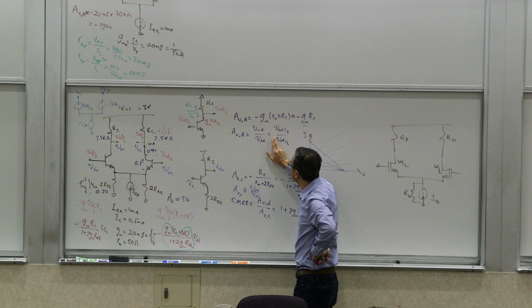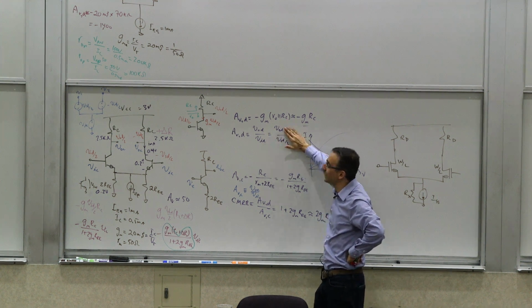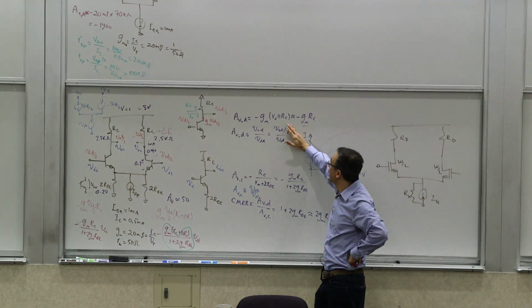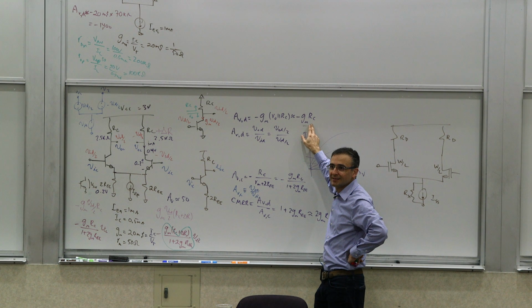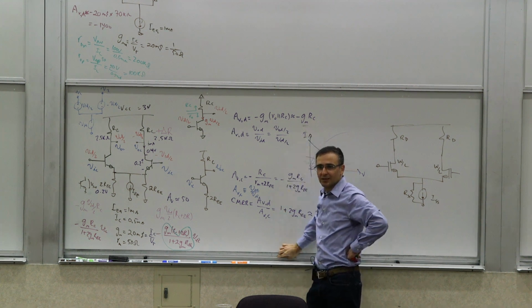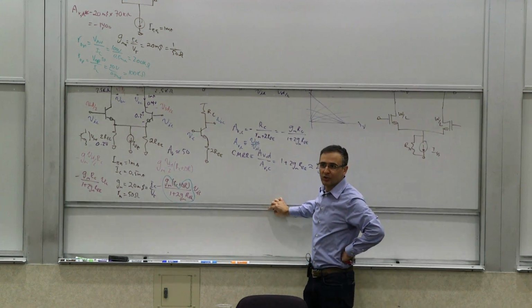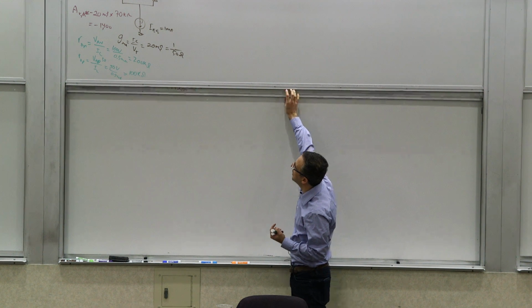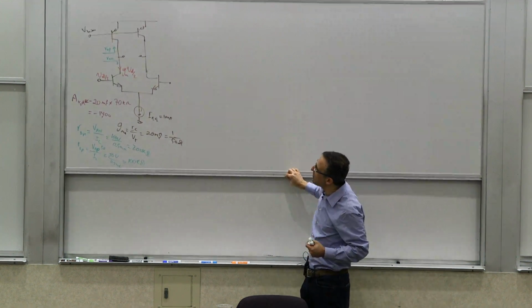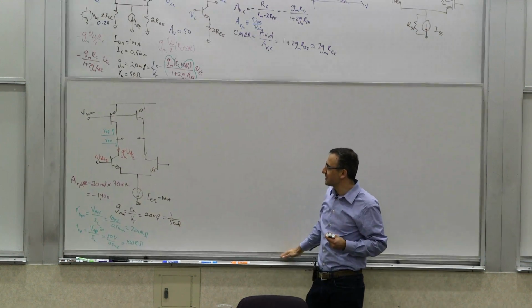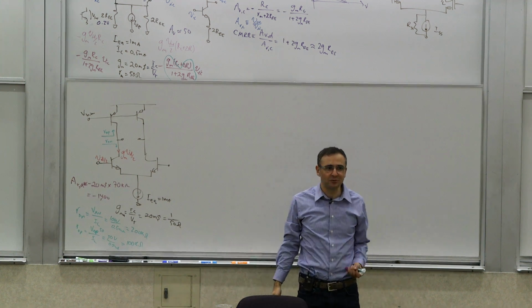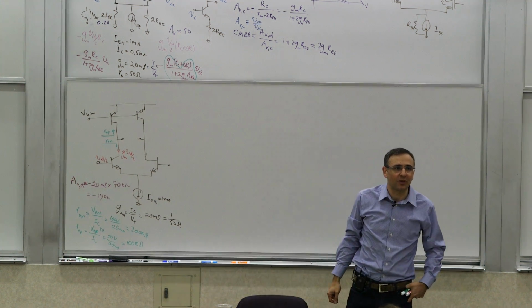So what you see here is twice the gain, because this is not here. So the gain will be half of that as a result, right? So you get half as much gain. So 1400 becomes 700. You say, okay, I'm okay with that. I mean, that's plenty of gain, sure. If it's enough for you, you can take one output and then discard the other one.